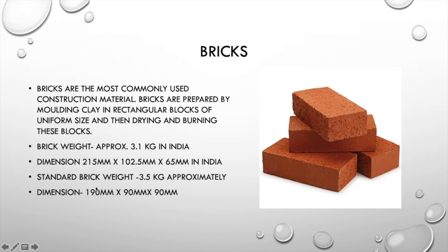material. The standard dimension of the bricks is 190 by 90 by 90 mm, and the standard brick weight is 3.5 kg approximately. But the brick weight in India is approximately 3.1 kg, and the dimension is 215 by 102.5 by 65 mm. Okay, so these are the two dimensions, and we mostly have to memorize these dimensions because these are frequently asked in the examination point of view.